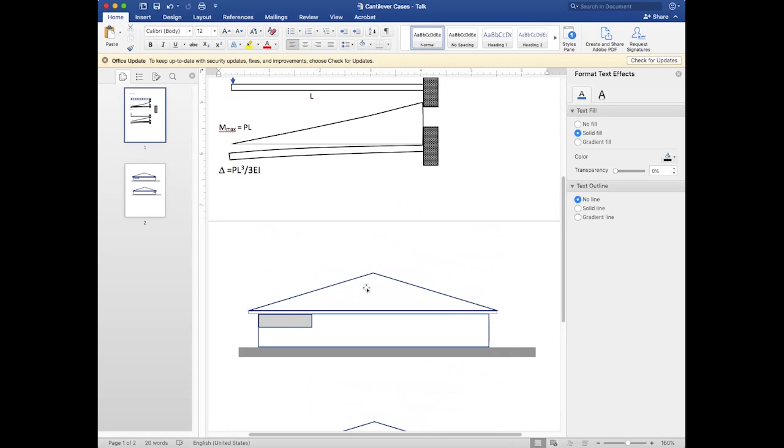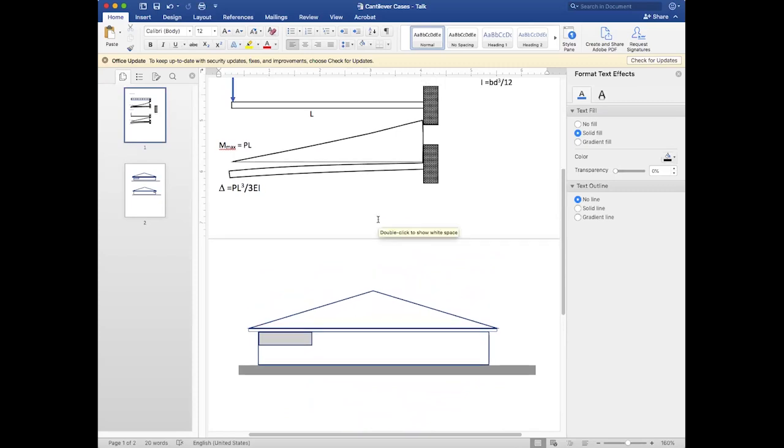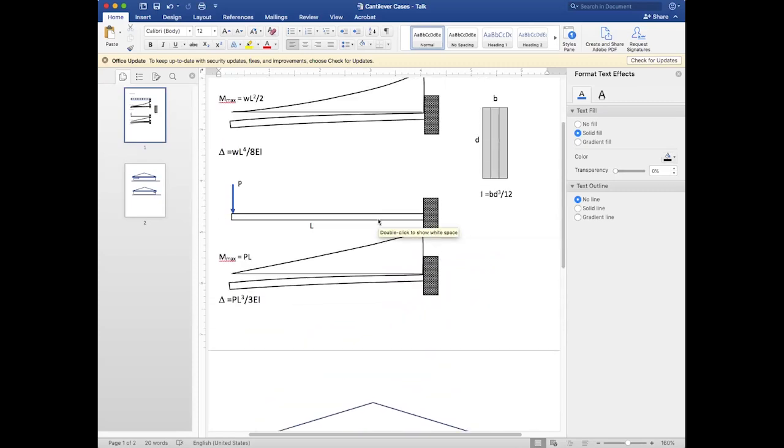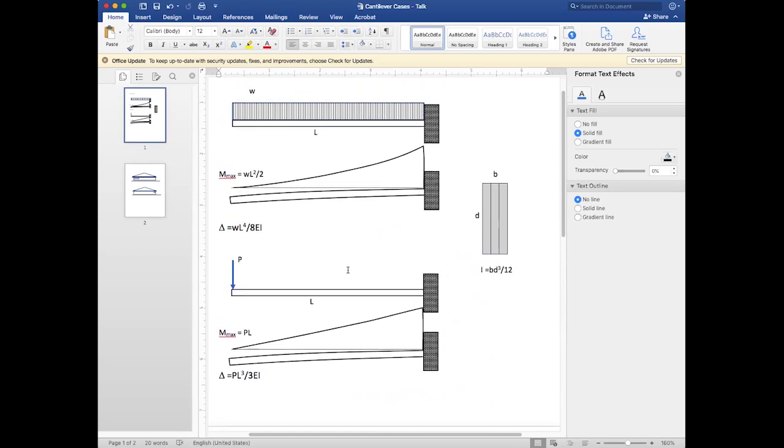I said, impossible. That's because when I was doing the calculations, I had put in an impact load. So I had doubled the normal gravity loads, and made the maximum deflection for this beam, instead of L over 240, I think I made it L over 1,000. So I was purposely coming up with a combination where the deflection would be so small that it would not interfere with or destroy the window.